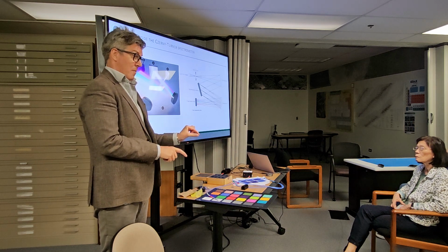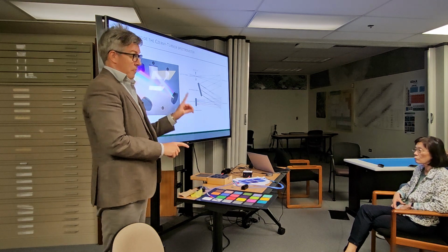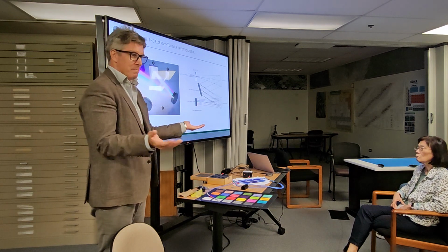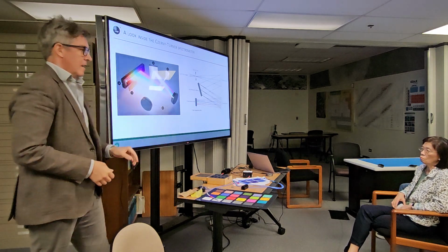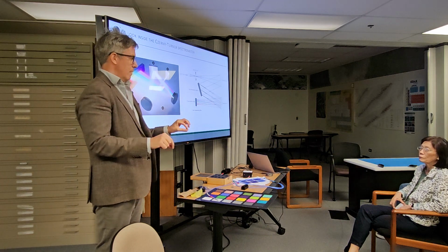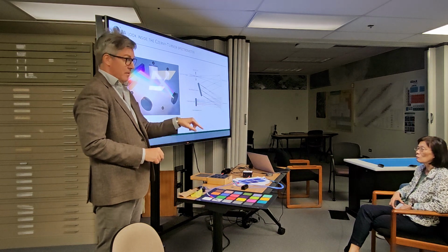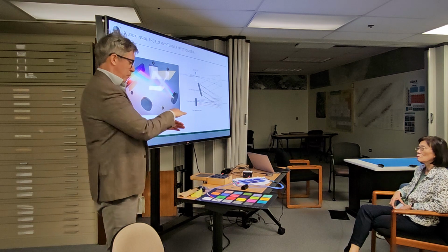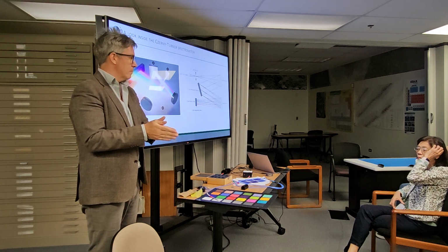During the integration time, we allow photoelectrons to fill the bucket. The more photons that strike that pixel, the more photoelectrons will be in the bucket. So with a CMOS detector, there is a gate and a bucket beneath every pixel in the array. Every pixel has its own gate, bucket, an amplifier, an AD converter, actually beneath the pixel. With a CCD detector, they whiz it all off to the end, and they do it at the end of the column or at the end of the row.